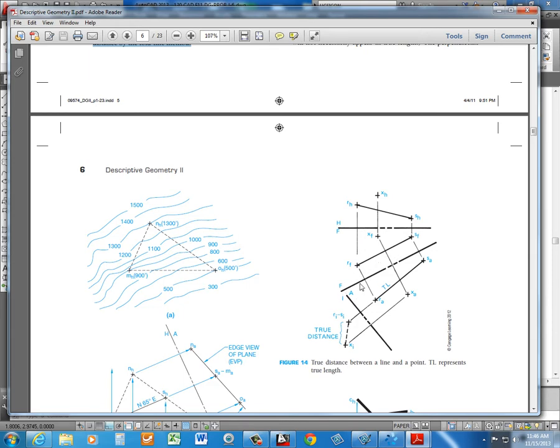So we do that by creating a fold line parallel to a given line, and then performing the projection where we measure true distance in the adjacent plane. You can think of it as two fold lines adjacent, so 1, 2, and then measure perpendicular to the points. And here's your measurement transferred. This measurement here to A, transferred from here, and that is to R, and then to S, measured here and transferred to here. Then connecting those 2 points, creating the true length line.